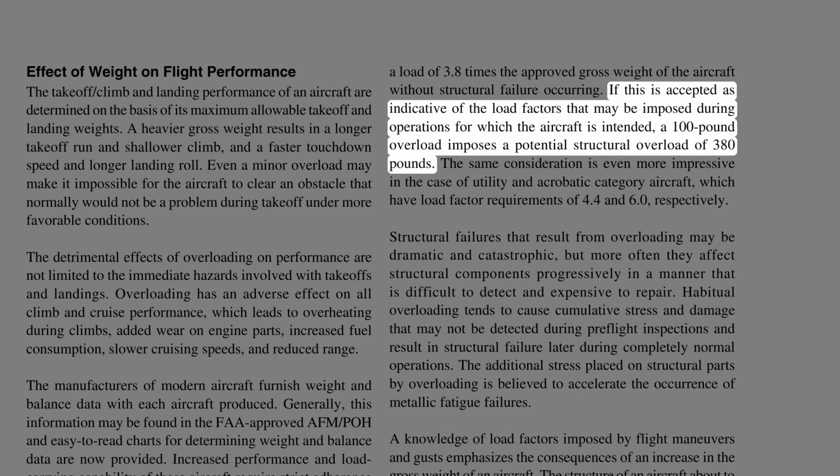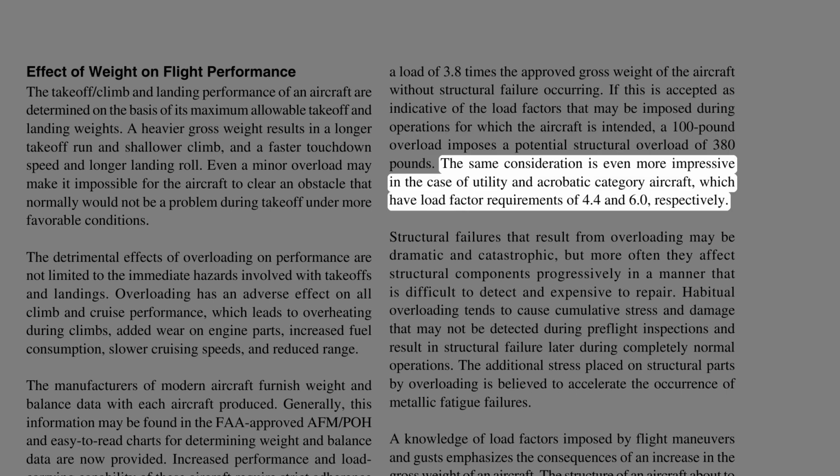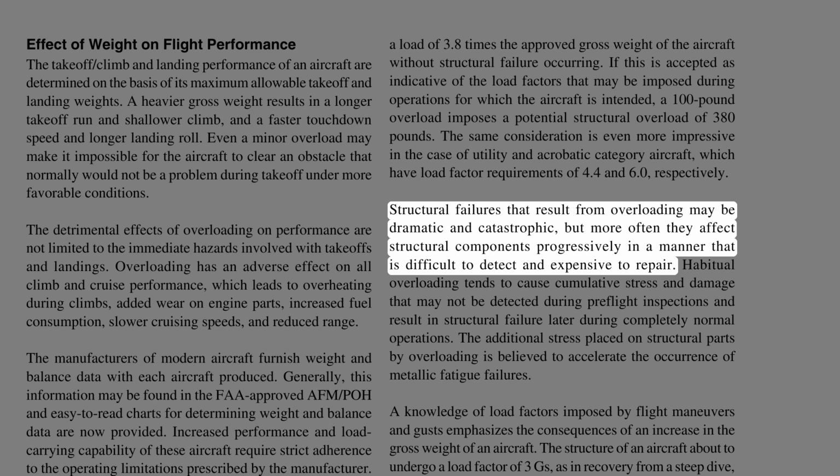If this is accepted as indicative of the load factors that may be imposed during operations for which the aircraft is intended, a 100-pound overload imposes a potential structural overload of 380 pounds. The same consideration is even more impressive in the case of utility and acrobatic category aircraft, which have load factor requirements of 4.4 and 6.0, respectively. Structural failures that result from overloading may be dramatic and catastrophic, but more often they affect structural components progressively in a manner that is difficult to detect and expensive to repair.